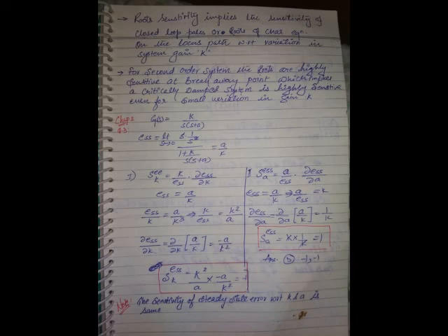Minimum value of reset time without instability arising means Ti marginal. We calculated K marginal earlier. Above or below the K marginal value, the system may become unstable. Similarly you have to find Ti marginal, and put in place of Td 0.2, whatever value you calculate.